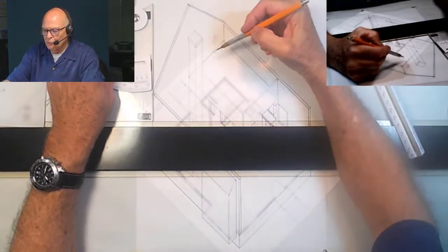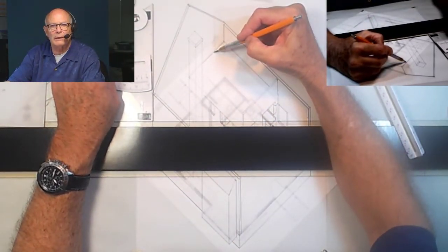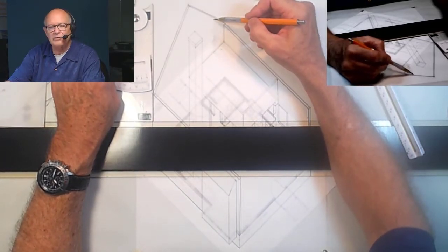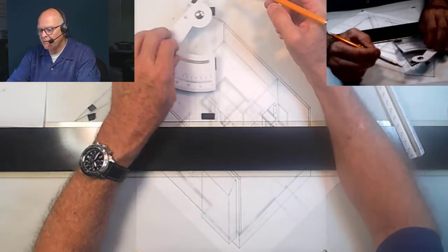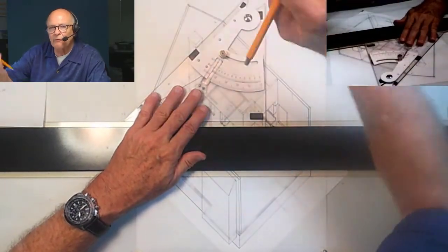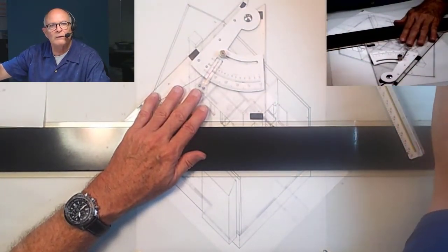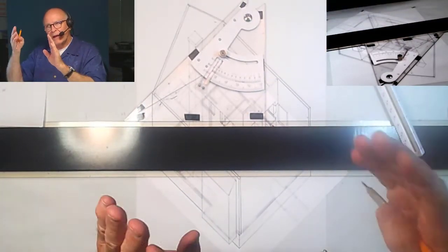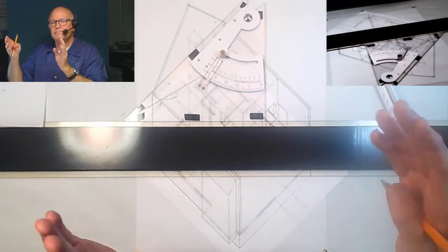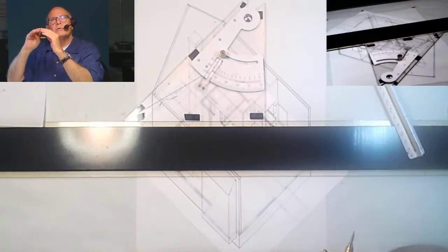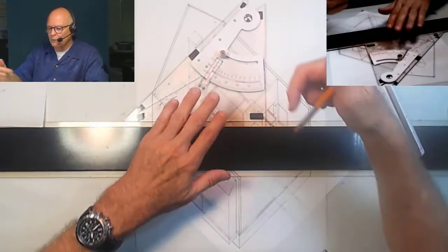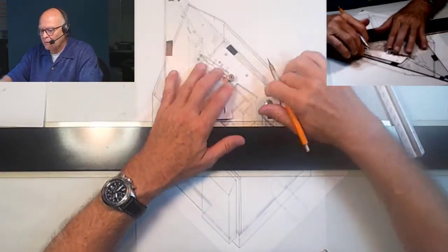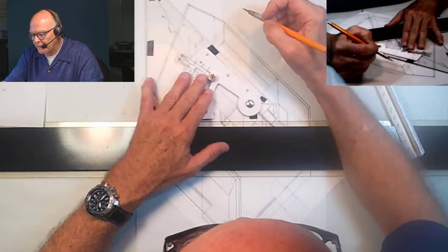So what we have to do is we simply extend the walls up from each of these edges, take it all the way up to the inside roof line, and then we're going to, at the far roof line, at the far vertical line, which is that inside edge of that alcove, we're going to then project back at a 45-degree angle. And that's going to give us what that wall actually looks like.